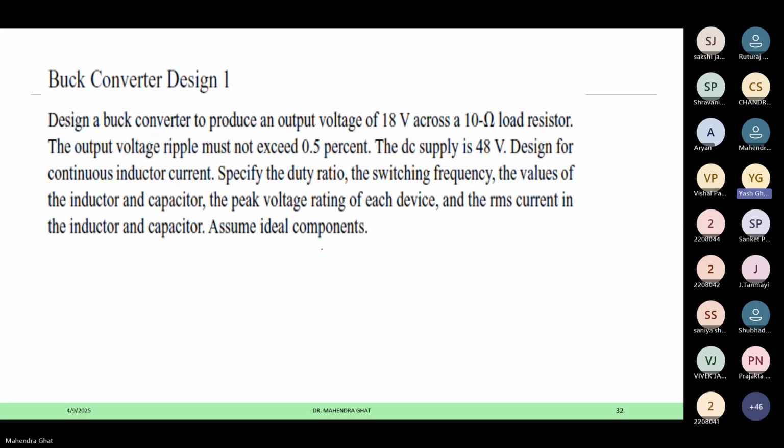Okay. From then, for the inductor selection, I have got a 208 microhenry value of the inductor. 208? Is this the L minimum you are saying? L minimum, it is higher. Maybe you made some mistake actually. For 100 kilohertz, at least it should not be that much. Sir, actually it's 20.8 microhenry. Okay, 20.8 microhenry.